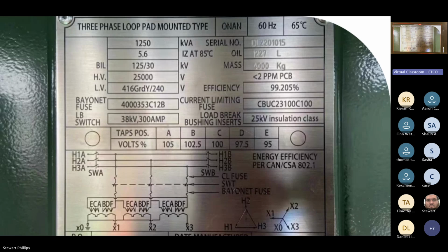It should do, but remember the fuses are HRC fuses. So they're not designed to trip within 4 hours at 1.5 times its rated current. The fuses can allow 1.5 times the rated current for up to 4 hours.